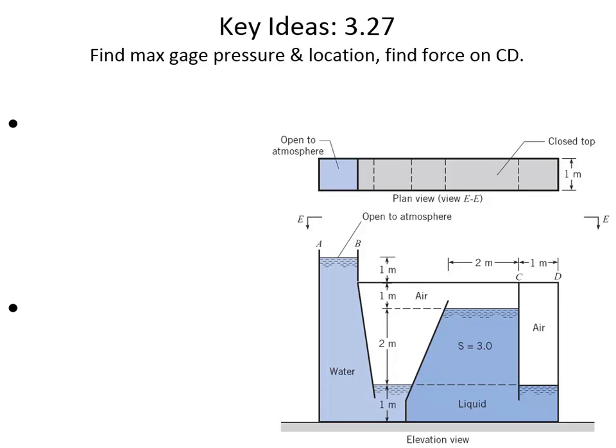So you could go down some distance and find the pressure here, and they've given you the dimensions you need to do that, because remember they've got that 1 meter here, another meter, 2 meters. So you can find the pressure here, and the pressure of the water at this elevation is also going to be equal to the pressure of the air everywhere inside of here.